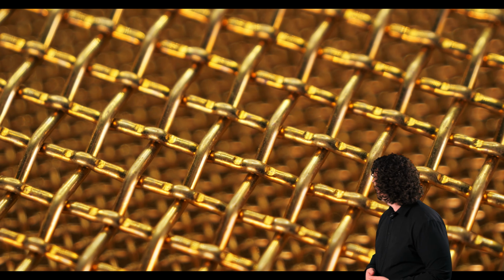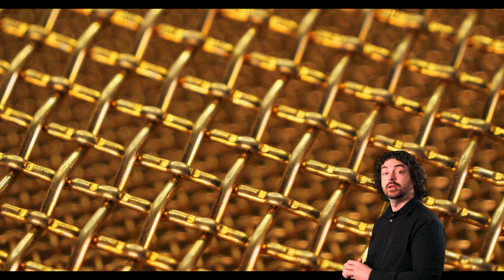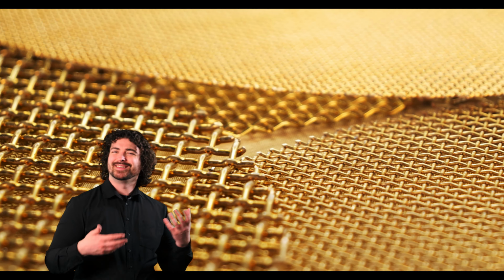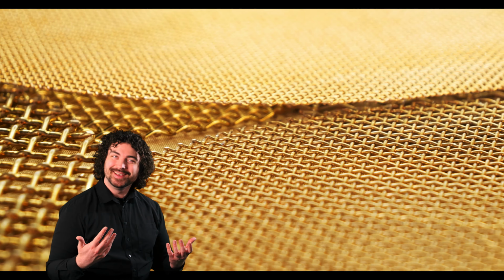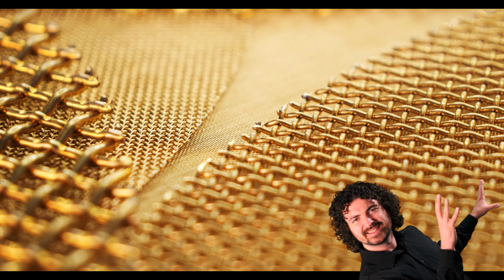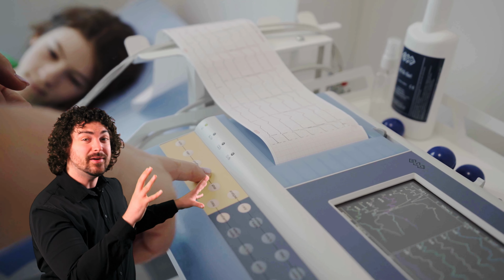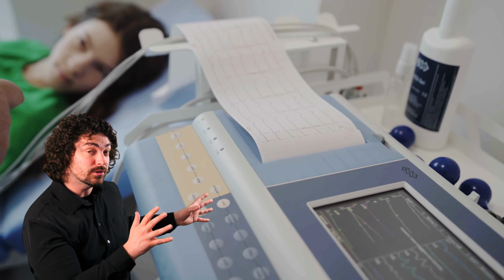Now you might be wondering, what about brass? Well, it's pretty. No, it has its place, but it generally falls into the same thing as stainless steel, only worse. It's a little corrosion resistant. It's a fairly good conductor of electricity. It's non-magnetic, which can be very important sometimes. It does have this really interesting antimicrobial property, so it's very useful in the healthcare industries for medical equipment. It's used heavily in the particle analysis industry, mainly for those last two points actually.